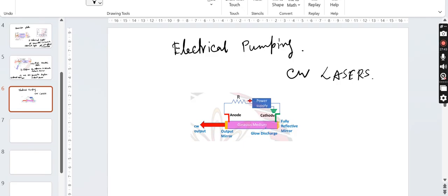The mechanism of transferring energy is similar to that of a fluorescent light source here. The stray charges, primarily electrons, get accelerated due to the impressed field, gain kinetic energy, collide, and cause further ionization, resulting in a glow discharge filling the entire volume of the gas enclosed in the dielectric housing.